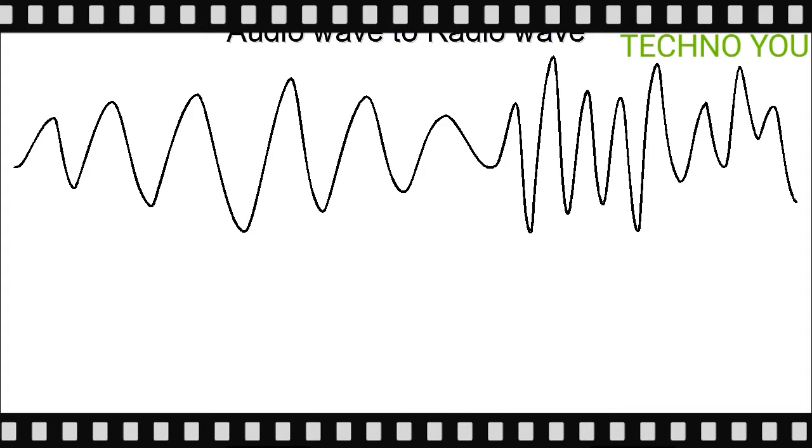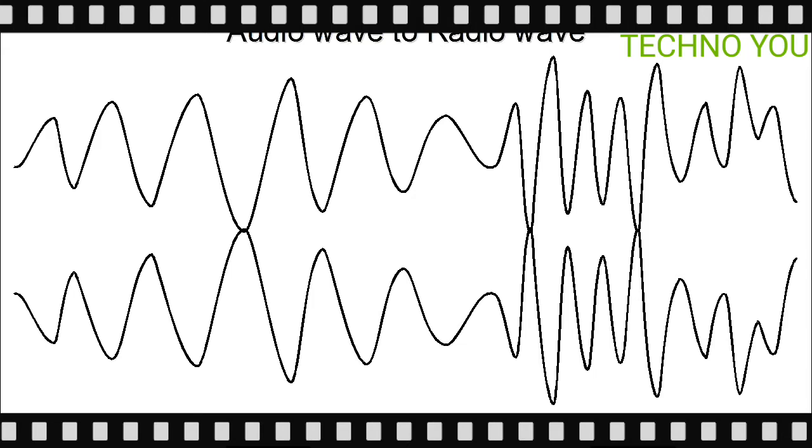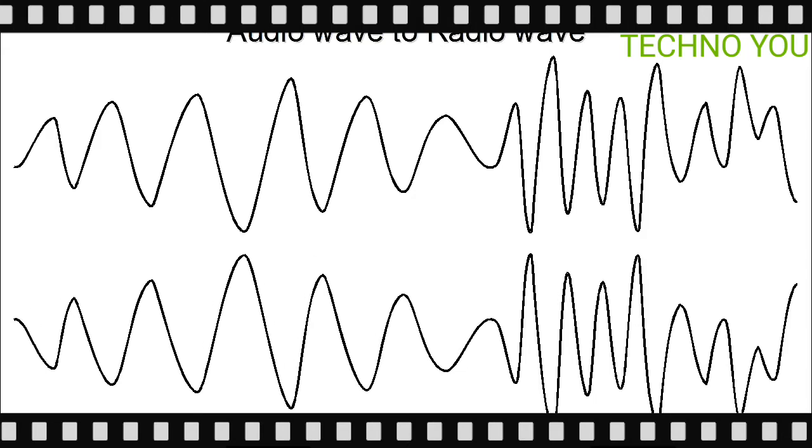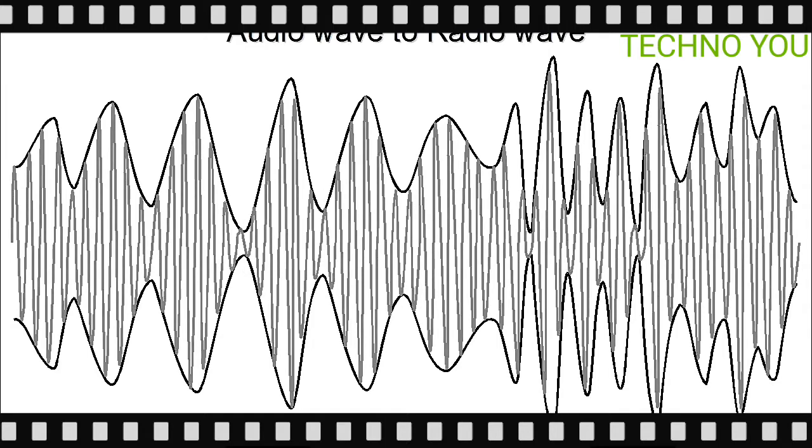They take the audio wave that they want to send and make a copy. They then flip this copy upside down, so it's a mirror of the first one. They also separate them out a bit so that nowhere do they overlap. Next, they create a wave that is all the same frequency everywhere and fit it inside the gap left by the original two. Of course, to do that, it has to be a higher frequency, so it can make a good fit inside everywhere.